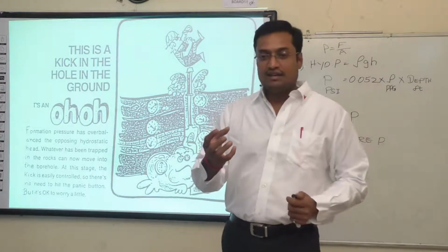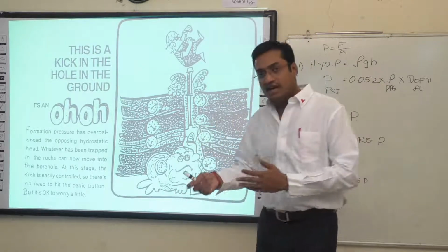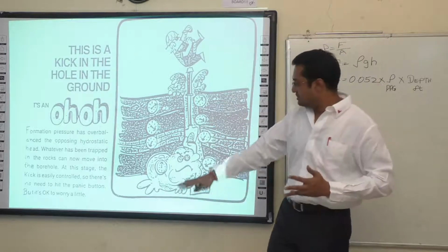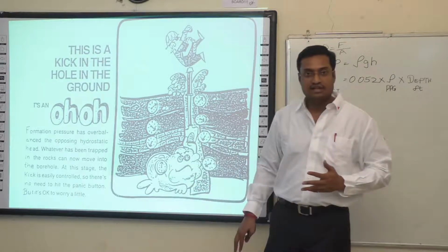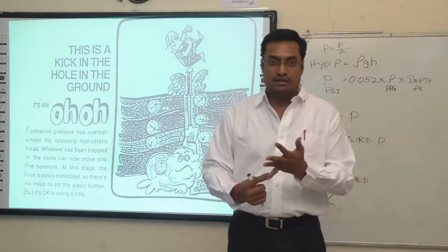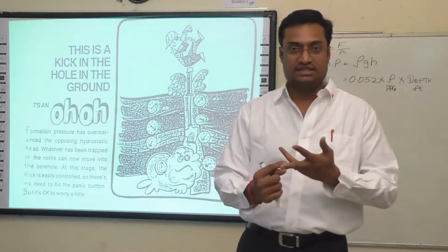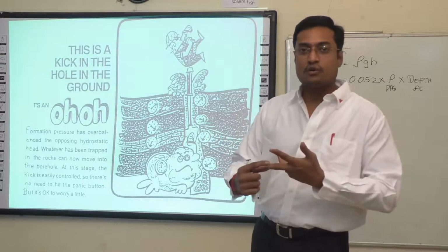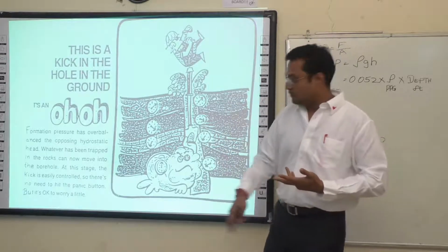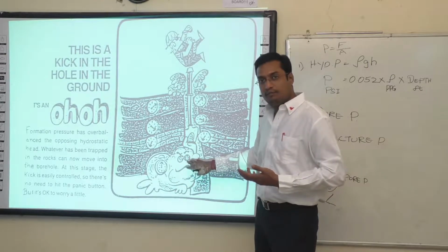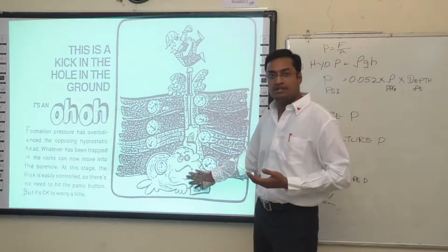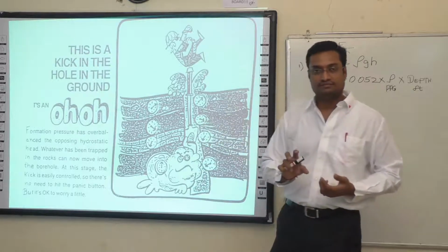A kick is an unwanted, uninvited guest inside the wellbore. The formation fluid, for that matter, can be oil, water, or gas. Any formation fluid which is entering into the wellbore in an underbalanced condition is called a kick.